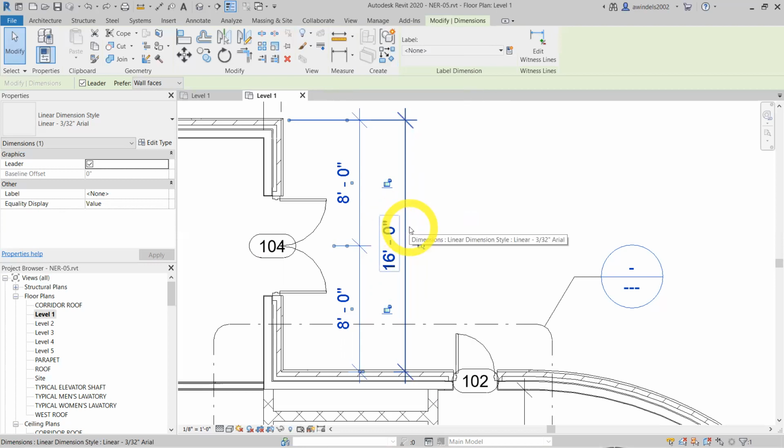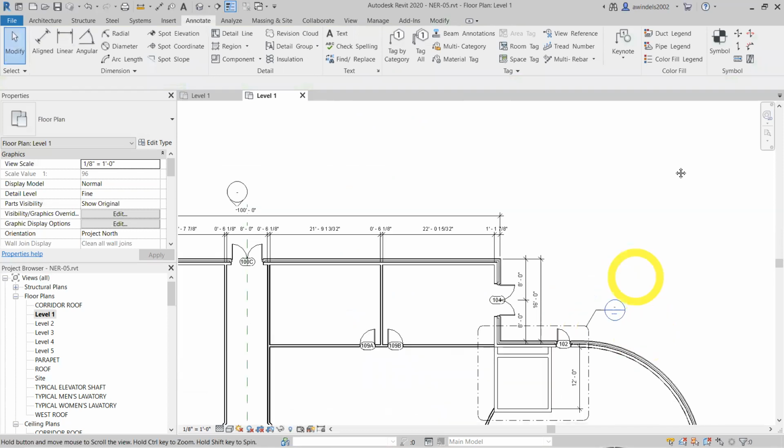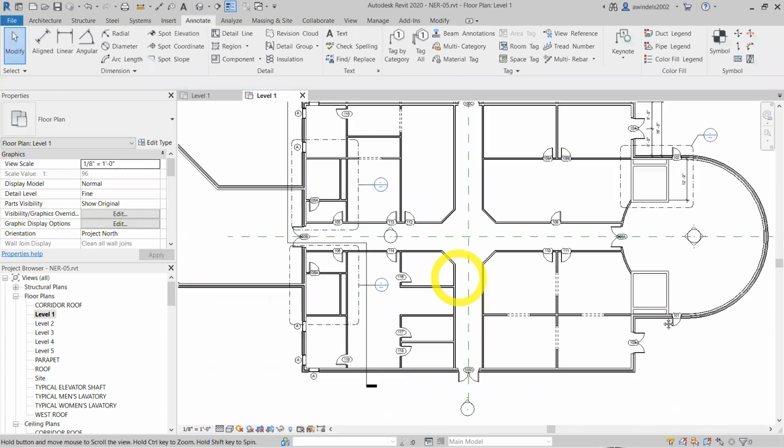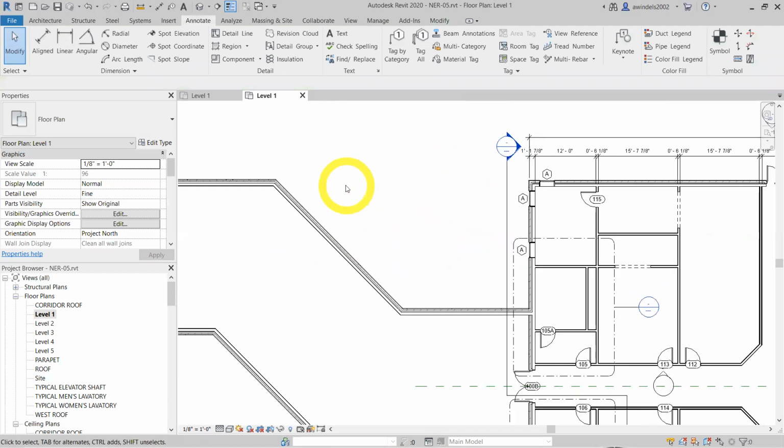This isn't really the easiest thing to do. We're going to use the align dimension for a wall at an angle. Probably the most confusing part of this chapter, honestly, because it doesn't recognize this wall on an angle. So let's go through that. We're going to trick out Revit to add reference lines to dimension about, basically, is what's going to happen.